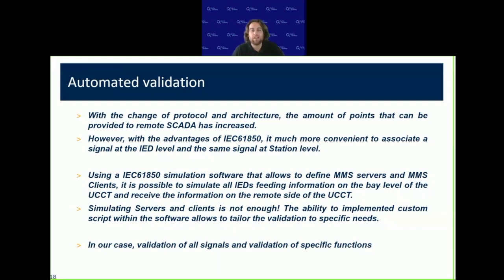So we are using a software that allows us to replace the IEDs as MMS servers and an MMS client that allows us to replace the remote SCADA, in order to validate that the UCCT is well configured with a third-party tool independent from the software itself. Now, those servers and clients are not enough. We need to implement custom scripts as well, and that's where this simulation software becomes very powerful: with those scripts, it allows us to tailor that validation to our specific needs.